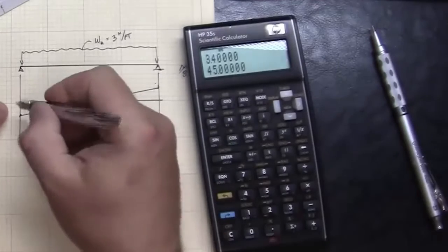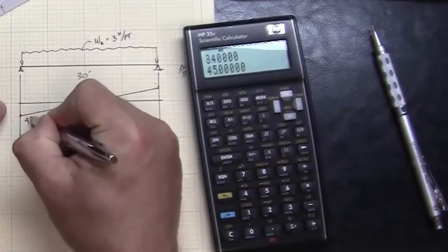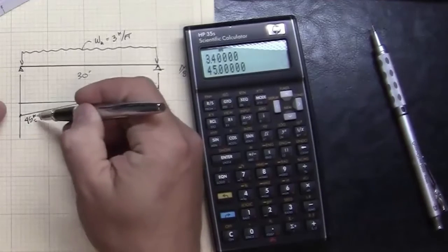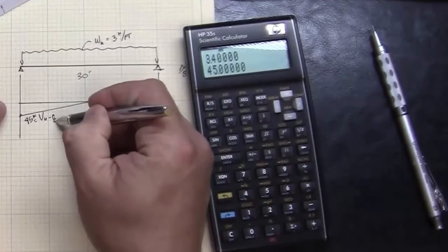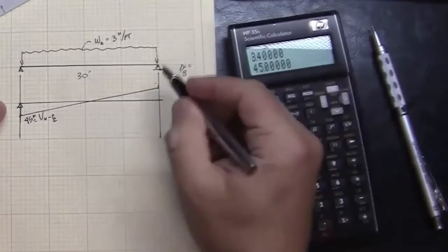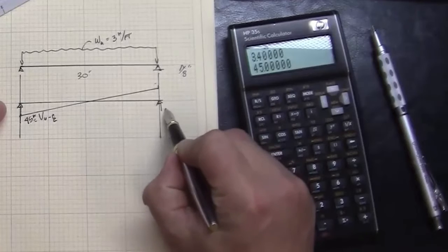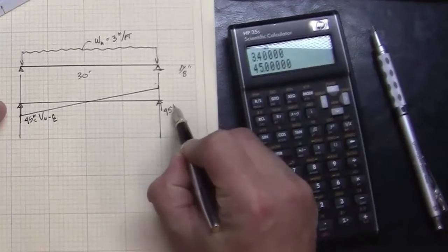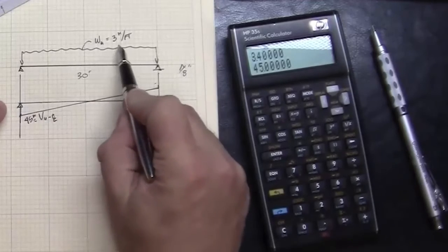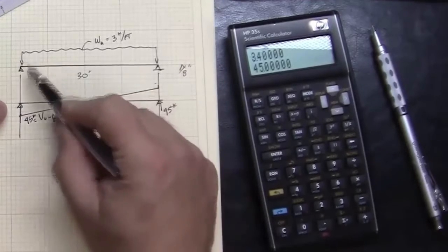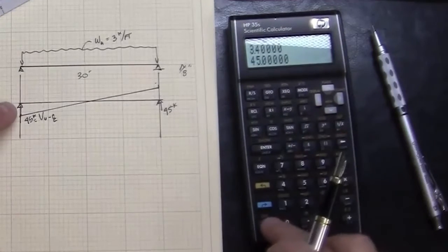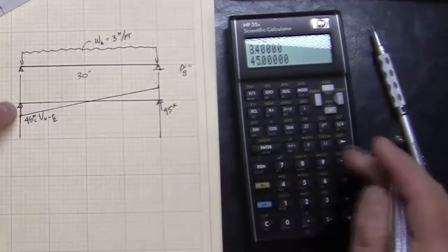I'm going to come up with 45 kips, and that is at center line. I'm going to note that with a center line. That's also the beam reaction, which we saw in the software. And then D away from the support, we could back off with the load and come up with a reduced VU at D away from the support. So that's VU at the center line of the support.